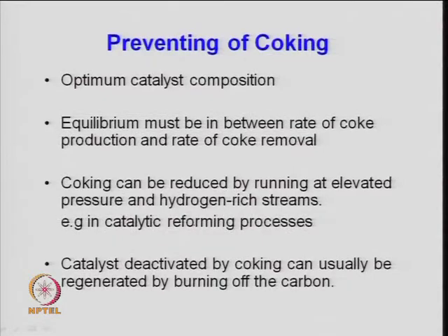When you look at a commercial refinery process such as cracking or hydrodesulfurization, the coke formation is to be removed, or minimized. So, you need to identify the optimum catalyst composition, because when the coke deposits, the activity of the catalyst drops. One can add some promoters in order to reduce the coke formation. Just like in cracking, a small concentration of potassium can be added, because the presence of potassium inhibits the coke formation, since it acts as a gasifying agent.